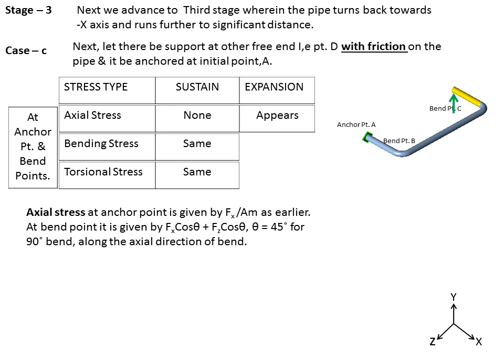degree over here for a 90 degree bend, we can simply have the bending moment over here as Fx plus Fz divided by root 2, and this one divided by section modulus and multiplied by stress intensification factor of the bend, we can get the bending stress at bend point B.